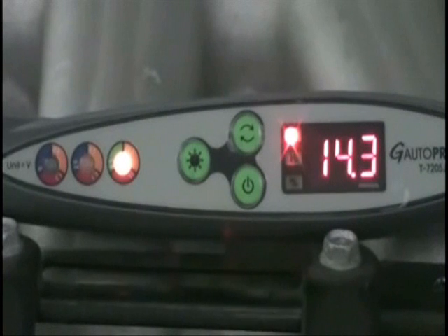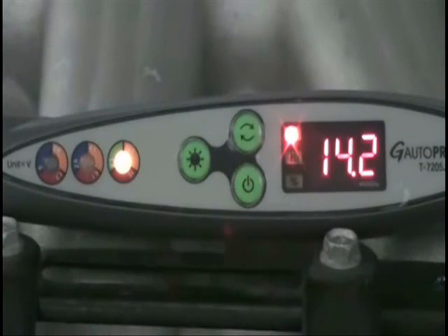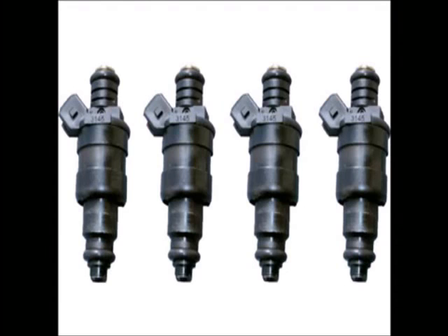One of the two wires connected to the injector is supplied positive voltage continuously. When signal and voltage of two wires are normal and injection on this injector fails, you can be sure the injector itself is out of order.